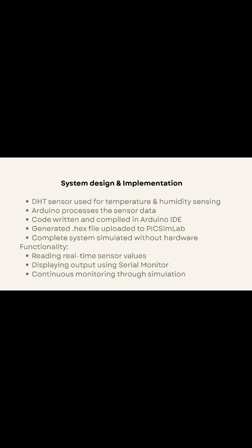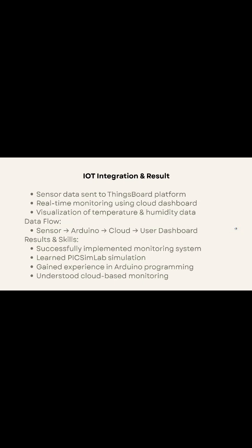Functionality: reading real-time sensor values, displaying output using serial monitor, continuous monitoring through simulation. IoT integration and result. Sensor data sent to ThingsBoard platform, real-time monitoring using cloud dashboard, visualization of temperature and humidity. Data flow: sensor to Arduino to cloud and to user dashboard.